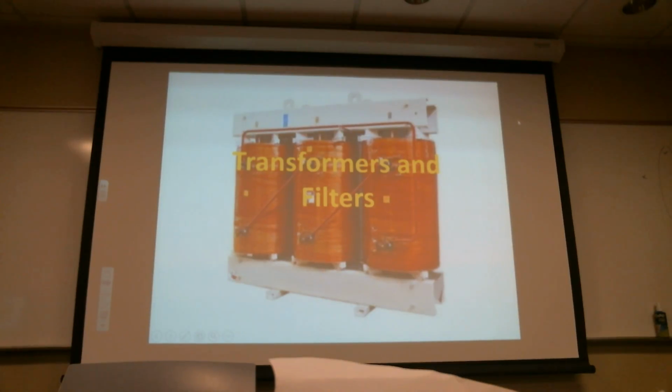Probably a really classic common one is pulsed DC to provide secondary ignition and spark ignition to spark ignited engines. That is a transformer, used in the DC world, but it's pulsed DC to create a somewhat constantly changing magnetic field.